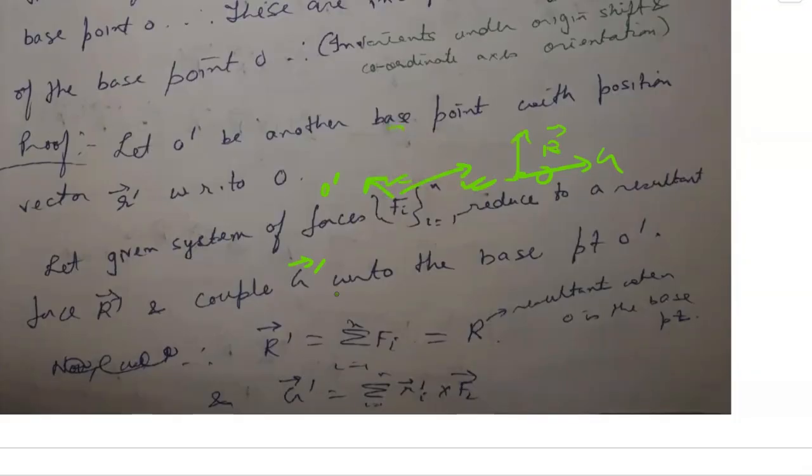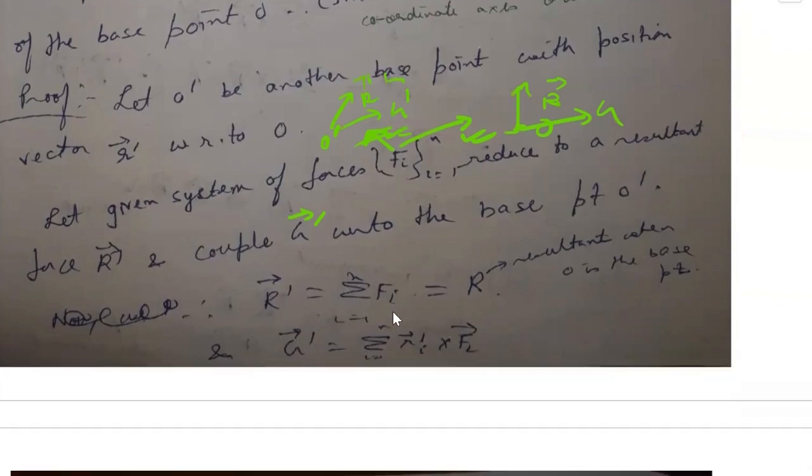This remains as your R dash and G dash. Okay. So now I want to find out its resultant magnitude, and the pitch of the wrench will remain the same. So whatever might be the R dash, it should be the vector sum of all these components of all these forces. So it should be equal to this one. I have already missed this direction sign. You have to be careful about it.